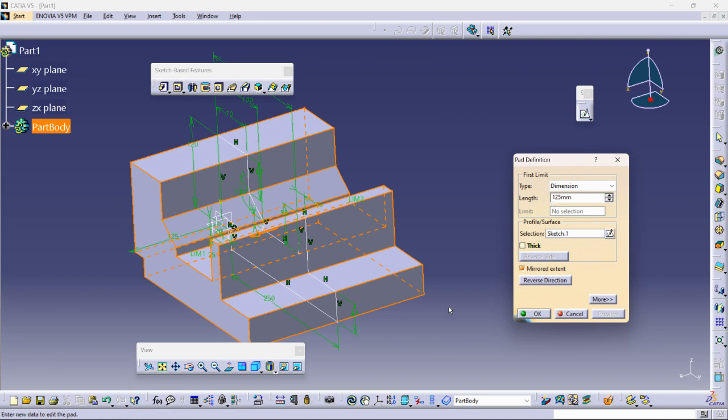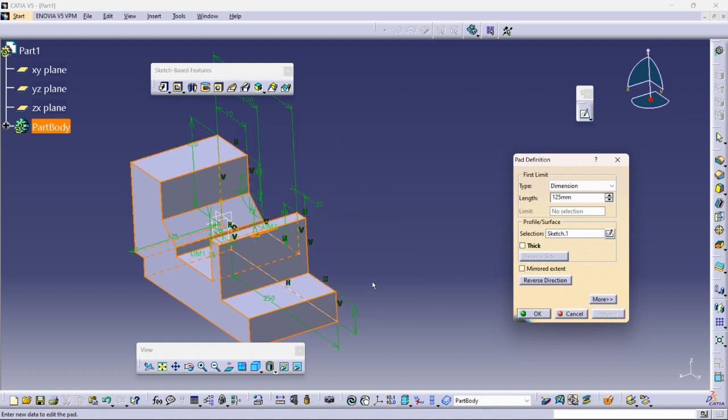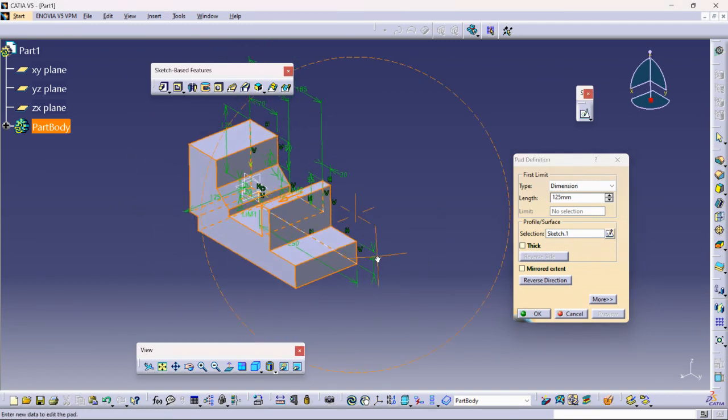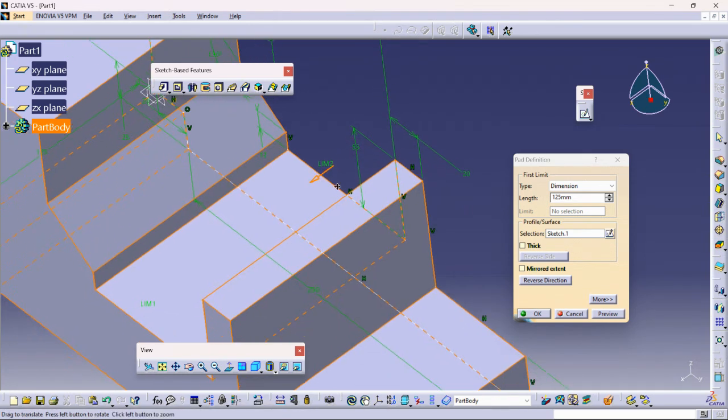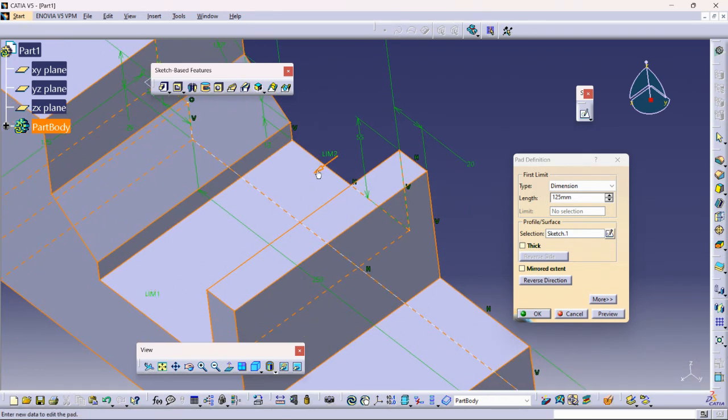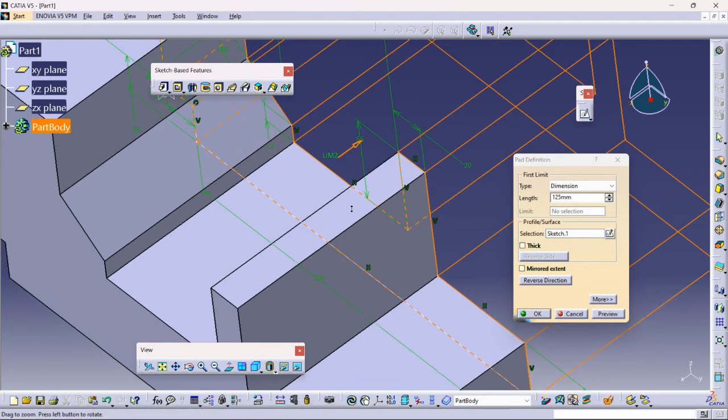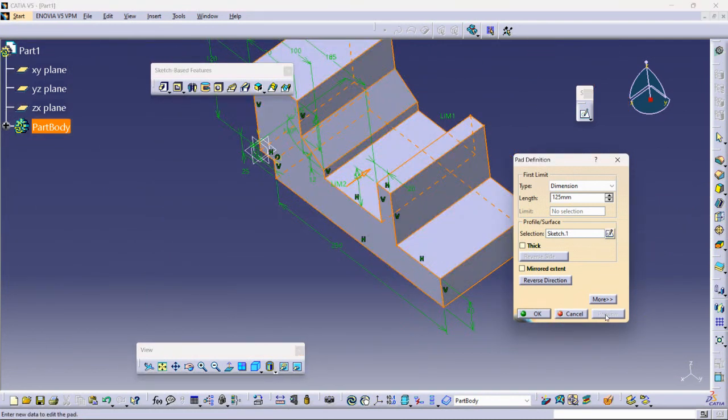Okay, the second limit is the neutral element. This sketch will be reflected here, and it will be padded with draft -10 in this way. Then there are a few drafting options here. If I have turned all these off, it will be like this. If I give a fillet in the second limit, this one, only there will be a fillet. If I give it in the first limit, here we will have the fillet. If I give the lateral radius, here I will have the fillets.